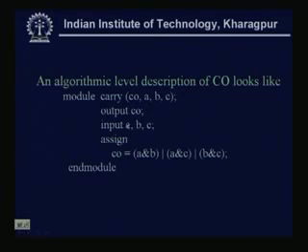Why 3 inputs? A, B, C: A and B are the operands and C is the carry in. Then this assign statement is my behavior, the function of how I can generate this carry output from here.